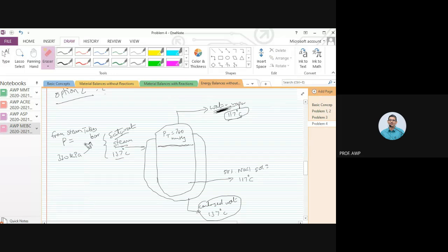Want to increase pressure? Want to reduce pressure? What do you want to do? Sir, then there is a problem in both directions. Correct. If I reduce it to 2 bar to increase the latent heat, this temperature will also fall. Then I will not get the 20 degree centigrade driving force that I wanted. In any case, I can't reduce it to too low a value, because then it will be less than the boiling point of water plus the boiling point elevation. So I can't do that.